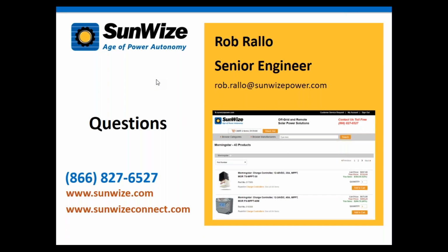So I think we've mentioned that before in some of the other webinars with regards to loads and understanding loads. But that's just another good example of this: if you've got a load that needs a tight regulated voltage in an off-grid system, you may need another device in there. Using a power supply may be great for the load, but not good for the battery, because the battery needs a wider range to operate, and the load may want a very tight range. So you may need to add an additional device between the battery and the load to take care of that, like the DC-DC converter. That's one of the tasks that it has there.